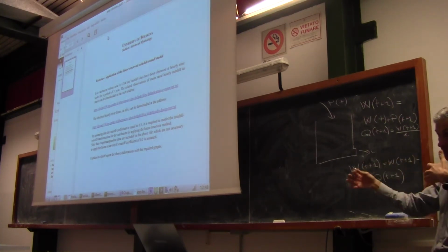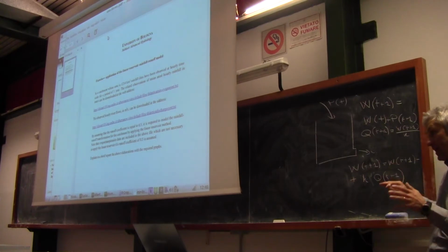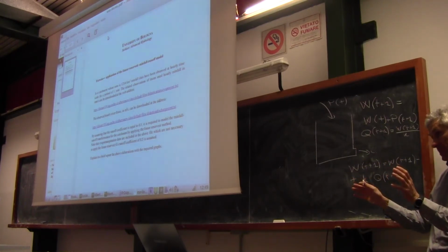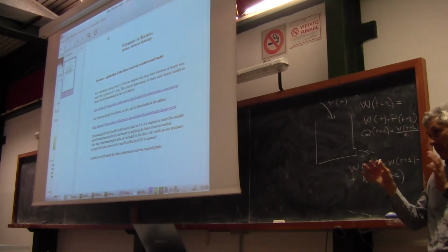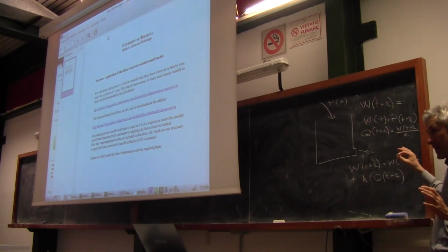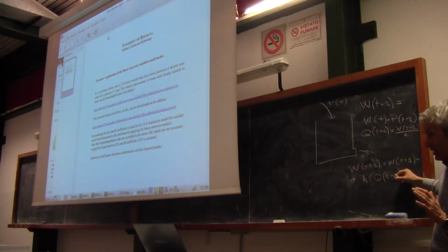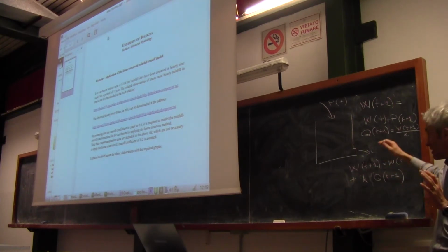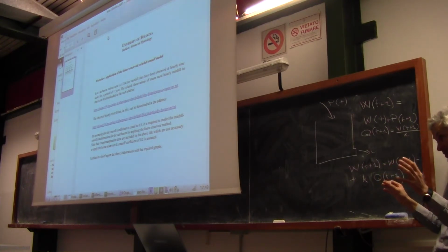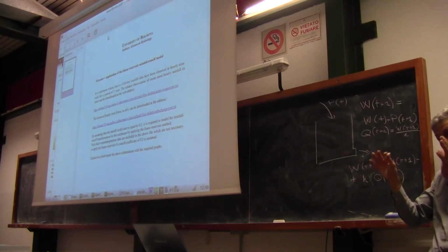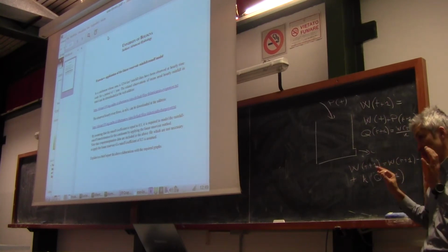What is the difference? The difference is due to numerical approximation, because in doing this, I am applying a finite difference method. I am moving forward for delta t time steps, not dt. This is not an analytical integral. What I'm computing here, look, it's just a summation. A summation is an integral. So I am indeed computing an integral here, but it's a numerical integral. So I'm not applying the analytical integration in order to get the solution of the linear reservoir. I am applying the numerical integration.